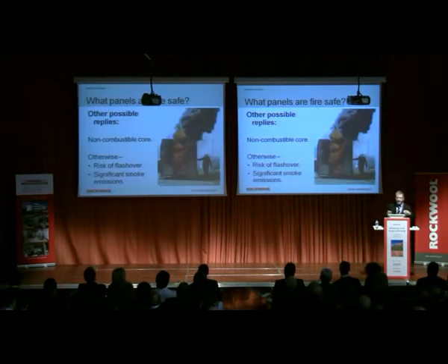If we ask as a user, what panel can I consider fire safe? Well, I can get a different reply. Of course, if the core is non-combustible, the construction is non-combustible as a whole, and the panel is safe at any fire, at any conditions. Otherwise, there is a risk of flashover. Here you can see the example of the flashover. And you have significant smoke emissions, not only on the fire side, but also on the other side. I will show you an example later.